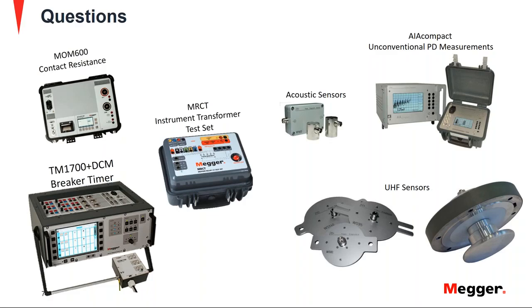Is the propagation of PD signal inside GIS happening through the conductor or gas? And what happened if there's an interruption by CB or disconnector between PD source and UHF sensor? That's actually a good question. The actual propagation is happening through the SF6 gas in combination with the enclosure itself, acting as a waveguide.